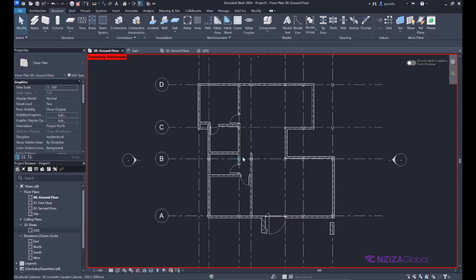So those offsets mean, for example, this is a column, and you want the column to go like 1 meter further above. We put the top offset, we put 1 meter. We add 1 meter, so it will be longer. Yeah. So for the base offset, if you want the column to go down from the ground, from the footings, anywhere down under the floor, we put the base offset minus 500, put it towards the top of here.